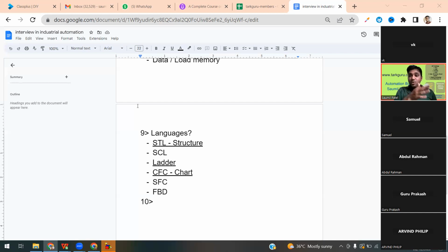There are other different blocks available in Siemens that you can use to minimize errors, like rack error, or a startup OB. Startup means whenever your PLC is started, at that time that OB runs, after that it will not run. So there is OB100, a startup OB. There are different OBs available, like programming error OB. These are the organization blocks you need to explain in front of the interviewer. But if you explain any one or two, that's enough, right?